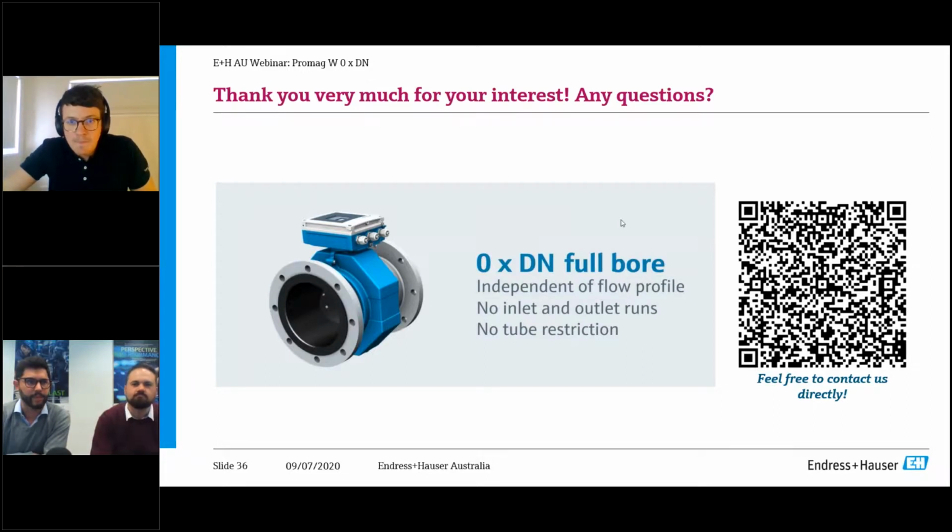All right, we do have another question from Dominic. What is the accuracy like at low flows or velocities? Yep, good question, Dominic. I displayed that third-party testing towards the start of the presentation. We found that the accuracy of these flow meters, particularly after bends, is very, very good, around 0.2, 0.3% error.